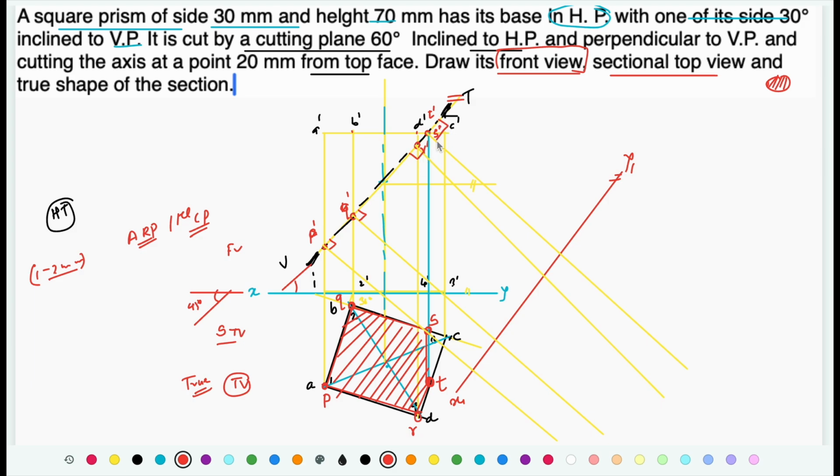We have taken projections from the front view. In some examples you might get the cutting plane in the top view, and in that case you will take projections from the top view. But for this example we have taken projections from the front view, so now we need to use the top view.